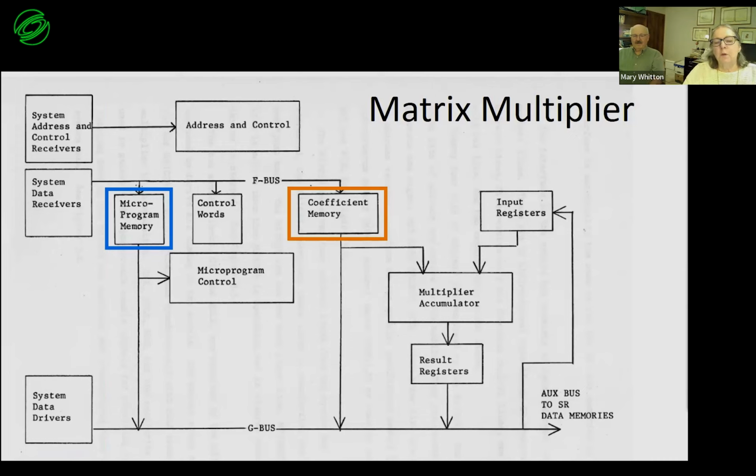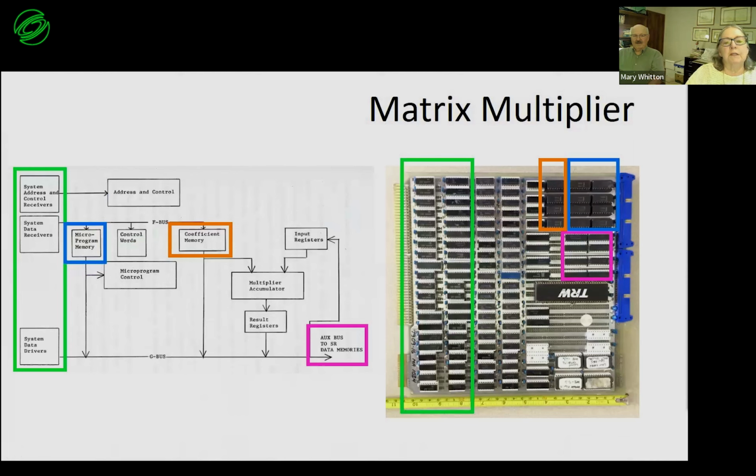It was a 32-bit wide instruction word, which was half as wide as the bit slice processor at that point in that incarnation. There were 12 fields in that word, and we used 31 of the 32 bits. Once the microcode and coefficients in memory were loaded, the processor just worked independently.